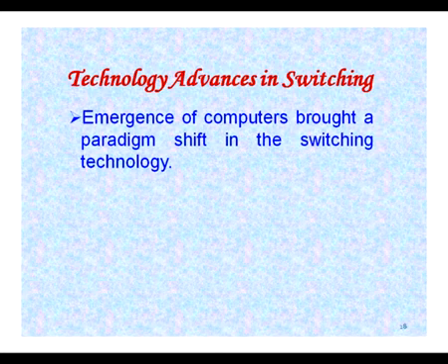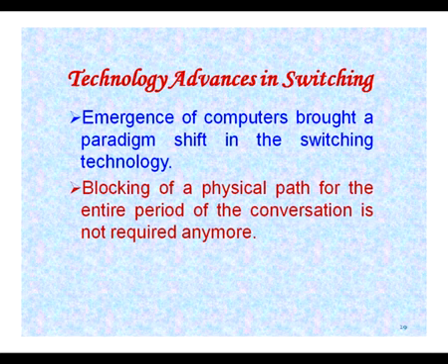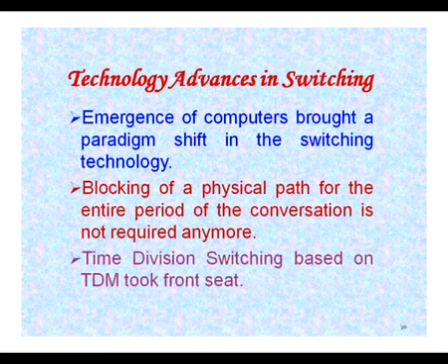Now the technology advances in switching have taken place. Basically, the emergence of computers brought a paradigm shift in switching technology. The physical path that was blocked for the entire period of conversation is not required anymore. Now we use multiplexing techniques, where sampling is done and only sample data is sent out. Time division switching is based on time division multiplexing, and that is the one very commonly used in present telephony.